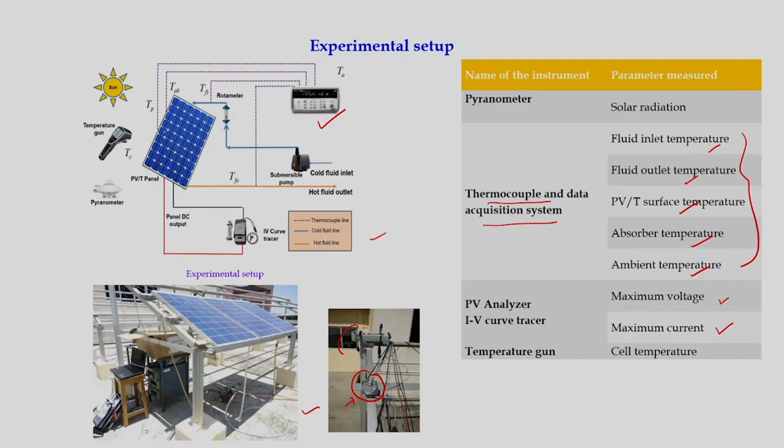So, here solar radiation is falling here, and then this is the collector we need to test, and we have to circulate known quantities of fluid. So, mass flow rate is constant, and then fluid inlet temperature is constant, and then outlet temperature can be measured, and we need minimum solar insolation of 700 watt per meter square. For these parameters we followed standards, right.